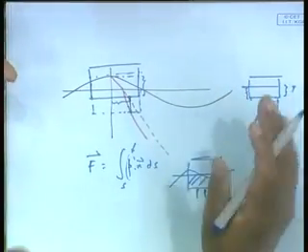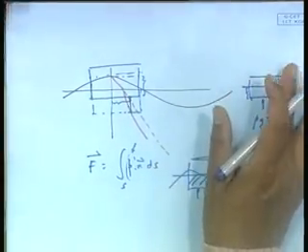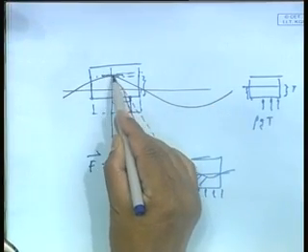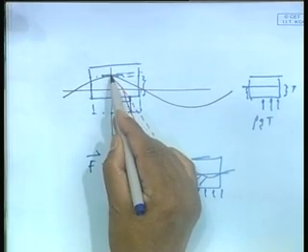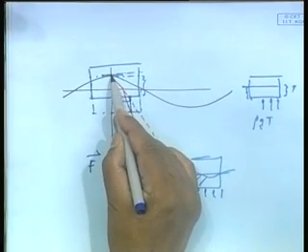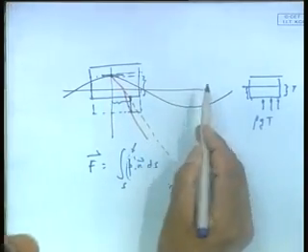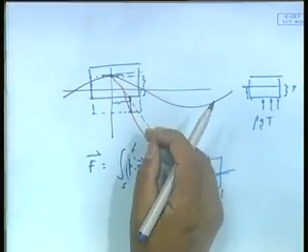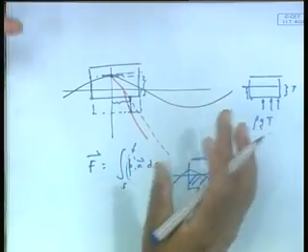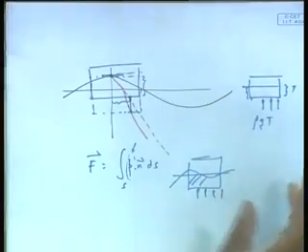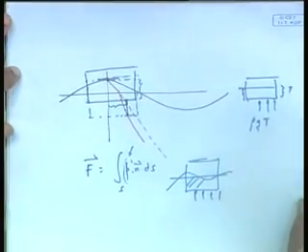So if I were to only use hydrostatic pressure, I will repeat again, you must use Z0 to be the variable axis measured from the instantaneous water line. If I was using a theoretically consistent value of Z0 to be the mean water line, then I have to use hydrostatic and hydrodynamic pressure together, not in isolation, because in isolation any of them cannot exist. This is one of the most important parts that we end up finding here. Okay, now let us see.